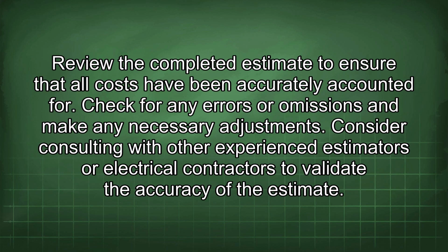10thly, review and adjust the estimate. Review the completed estimate to ensure that all costs have been accurately accounted for. Check for any errors or omissions and make any necessary adjustments. Consider consulting with other experienced estimators or electrical contractors to validate the accuracy of the estimate.